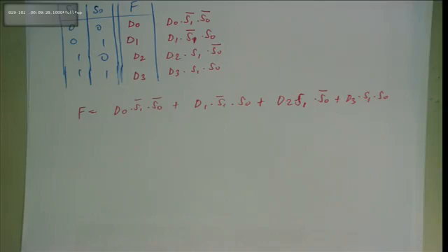That becomes too hard. Now if it was 16 data lines coming in, how many selectors have we calculated? 4 selectors. Output will always remain 1. So therefore how many inputs? It will be 16 plus 4, which gives you 20 inputs. So in your traditional truth table, how many combinations would you have? You'd have 2 to the power of 20 lines in your truth table. What is 2 to the power of 20? That becomes too difficult to handle, right? So that's why you'll do it something like this.